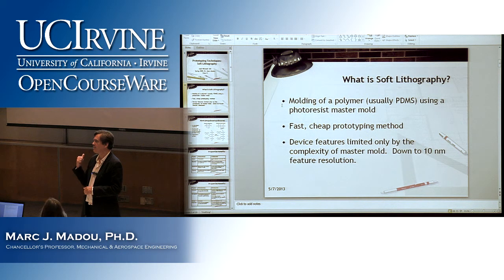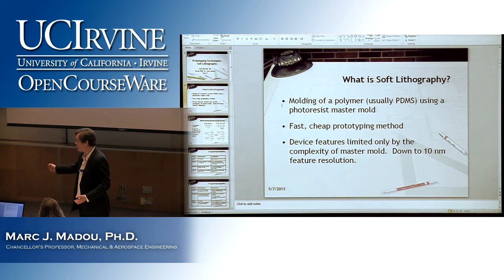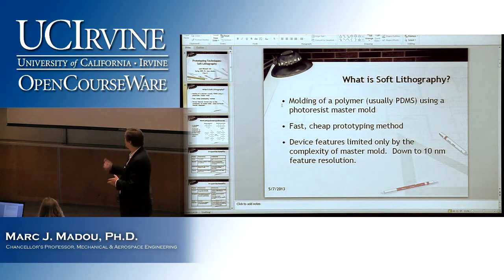What is the real power of this? It's stamping. The fact that you only need to make your stamp once, and so if that technique to make that stamp once is very expensive, who cares? Right? Because with that one stamp, you could make billions of products. And that's why a technique like this, if you make that stamp a bit tougher, could compete with lithography techniques, right?